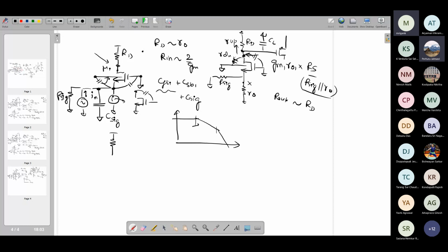If the input signal is voltage, then we will derive the input referred noise voltage. But if the signal is current, then we derive the input referred noise current. So once again, you can replace the ideal current source with a MOSFET, and this is having some VB. Suppose this is bias, AC ground, and this is also AC ground. So this is your VG1, this is your bias of the MOSFET of the current source.